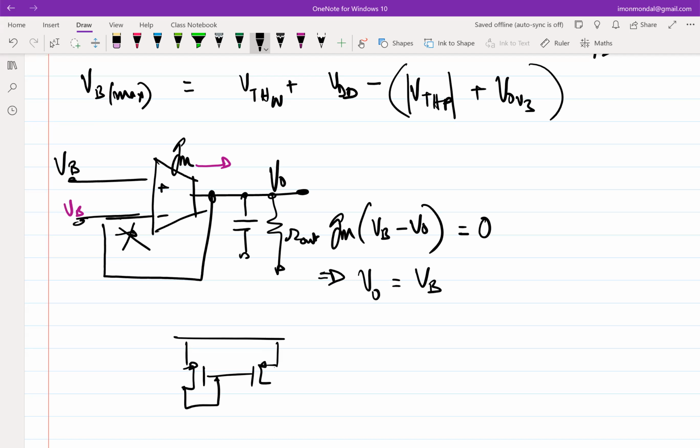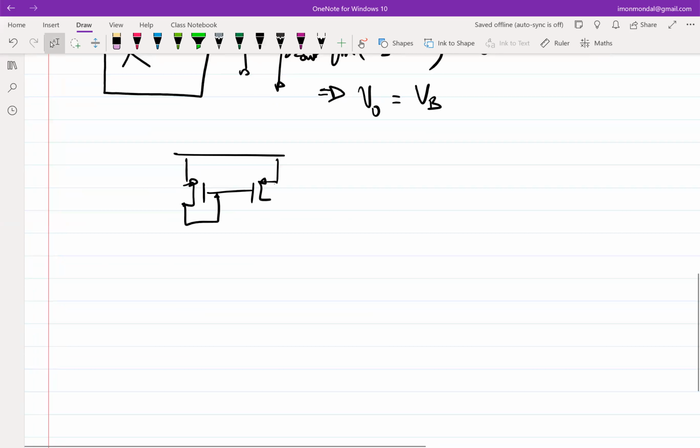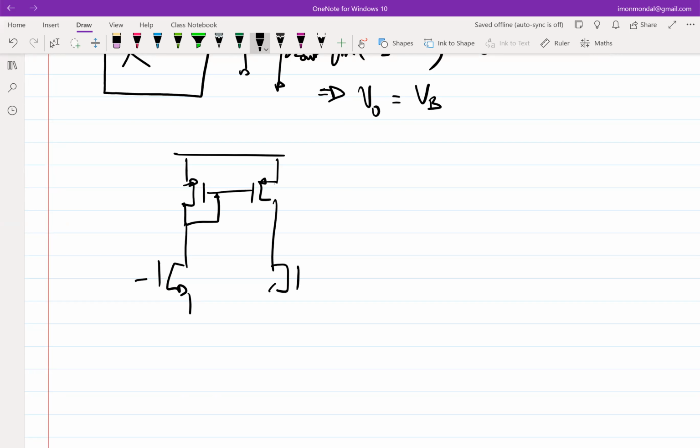So that's something you should keep in mind. Sir, we were modeling this as an opamp. Yeah, but an opamp also has the property of output impedance. This is not an opamp, that's why. But the loop gain is infinite. Right? So that's the critical difference. This is a voltage controlled current source put in negative feedback. Okay, so it's not an op-amp, it's a difamp, kind of.